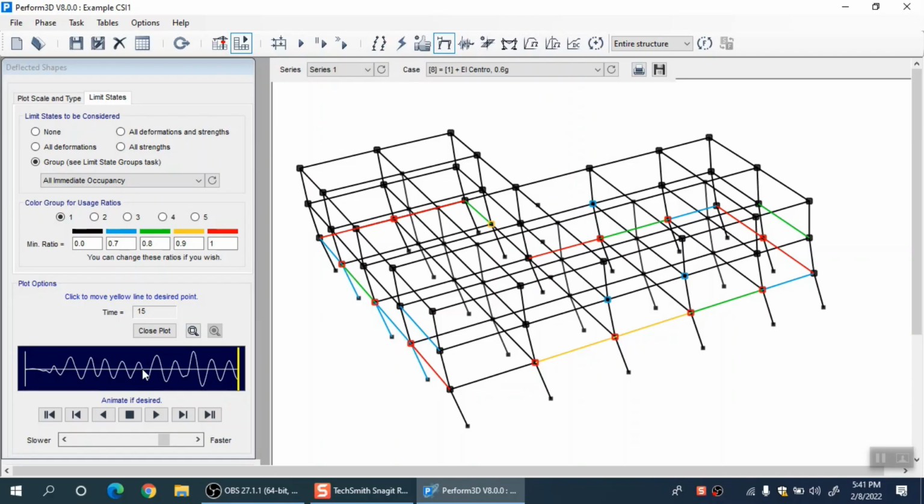Actually, in performance based design, you use the expected material properties, right. So, instead of reducing or accounting for a particular factor of safety, you try to be as accurate as possible. Unlike code based design where you reduce the capacities, in performance based design you increase the nominal material strengths.